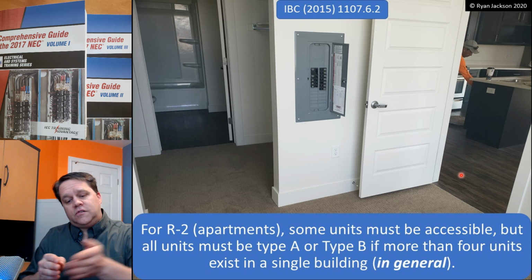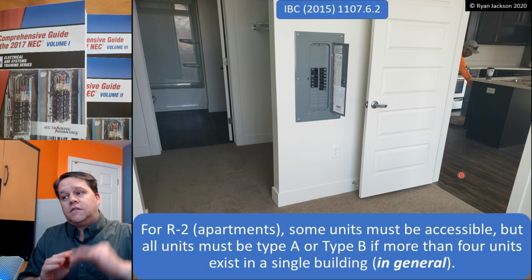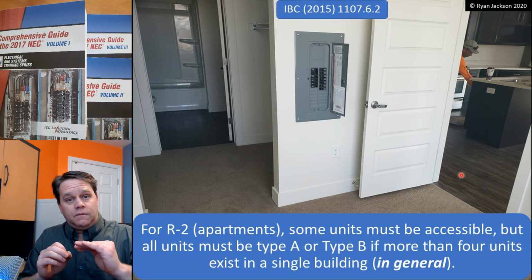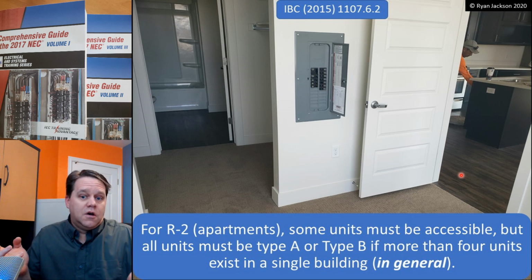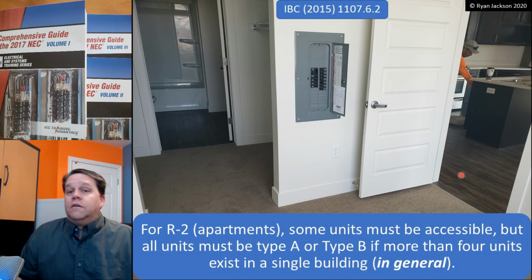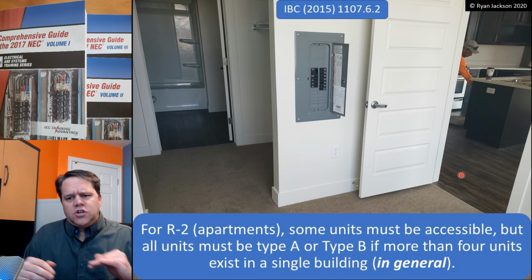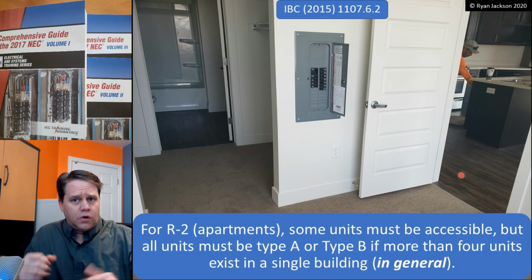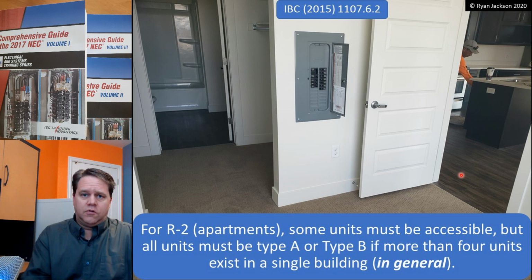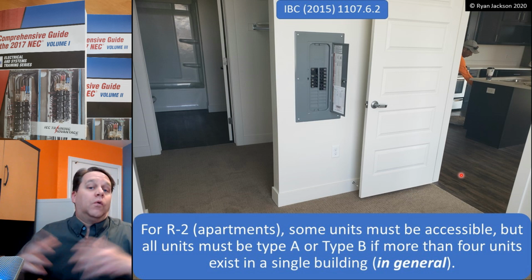My toilet has to be 16 to 18 inches away from the wall, but it doesn't have to be 17 to 19 inches tall. The reason for that is moving it farther away from the wall or closer to the wall is very difficult. That would require an extensive amount of remodeling. But changing the toilet to one that's taller or shorter is easy enough. I can rip out the toilet and replace it. So Type A or Type B are essentially adaptable units where I can make them accessible without ripping the building apart.